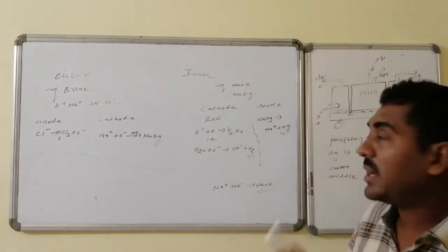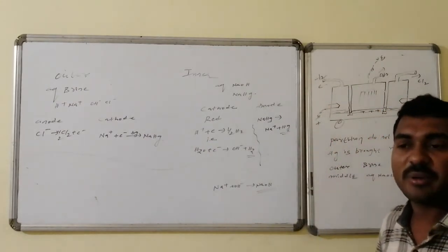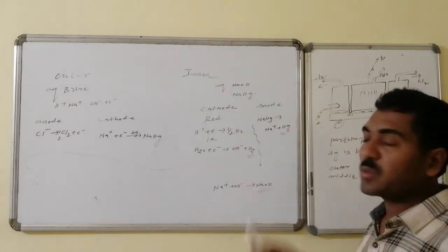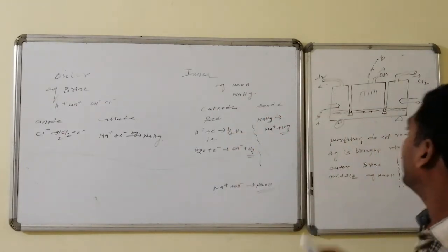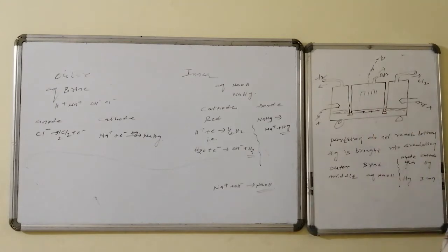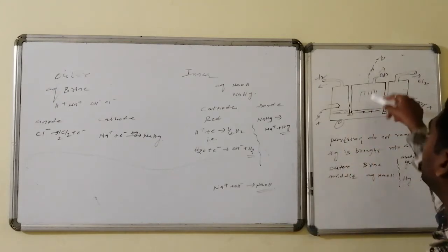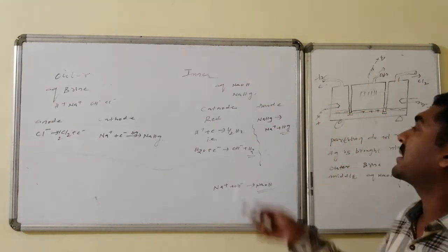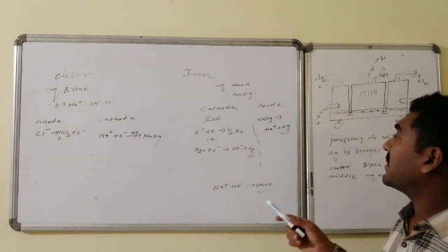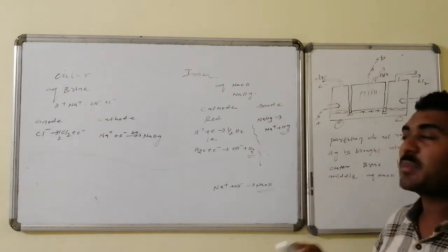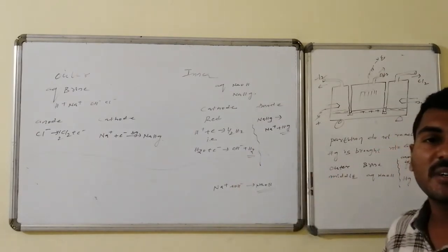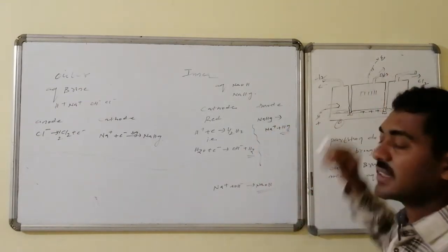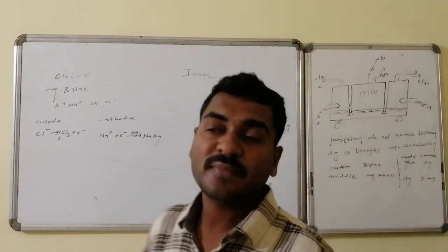Whereas in the inner or middle compartment we have aqueous sodium hydroxide, that is water followed by sodium hydroxide, and here sodium amalgam reaches the compartment. Here the iron rods act as cathodes and the mercury layer acts as anode. Therefore at the cathode reduction takes place. The H+ from water molecules takes the electrons and is converted to OH- ions followed by hydrogen gas. There is a proper channel for the liberation of hydrogen as a gas.